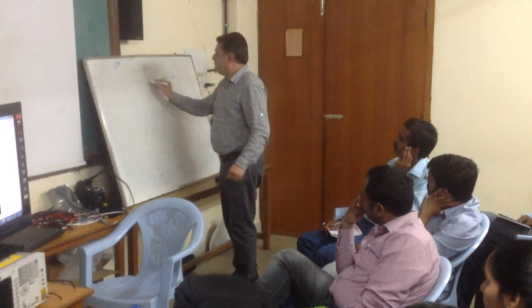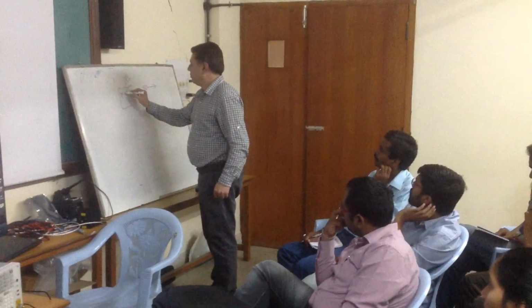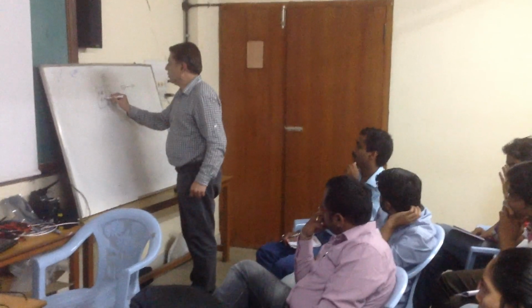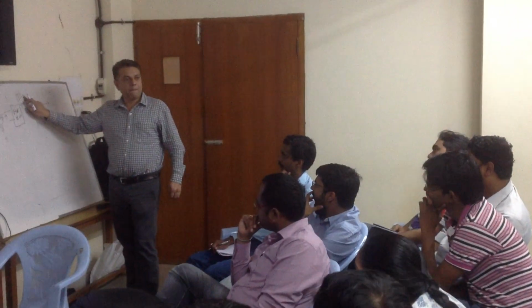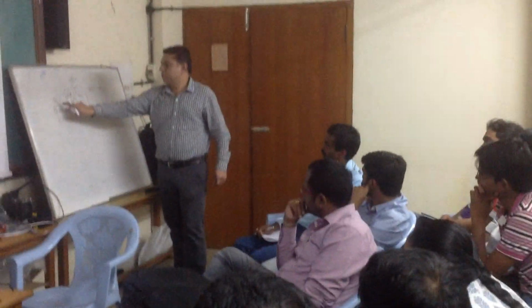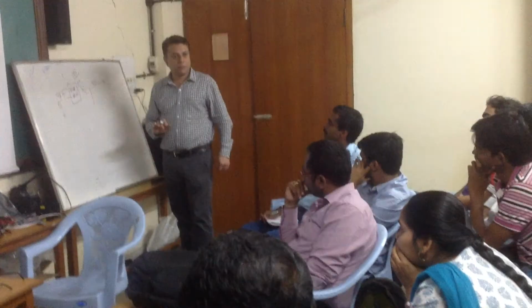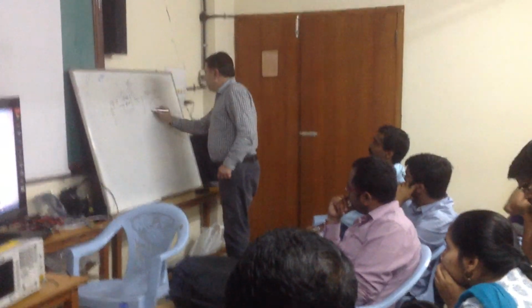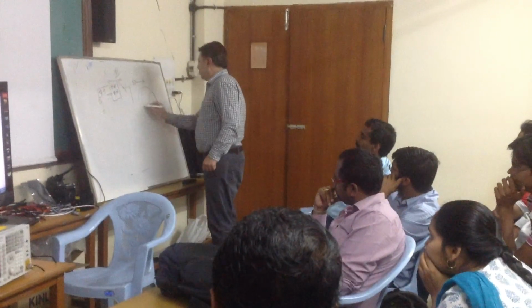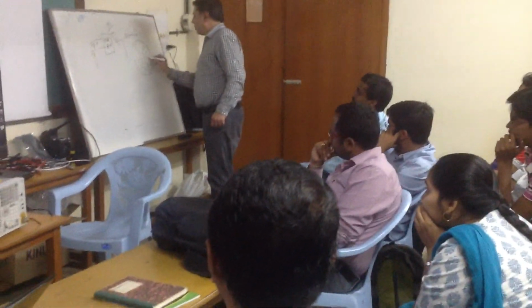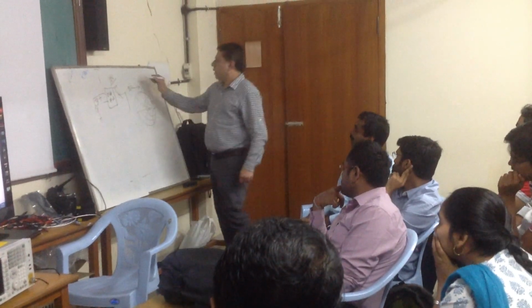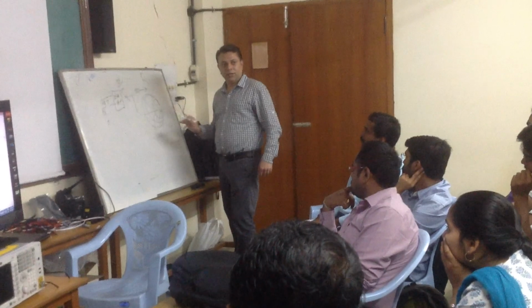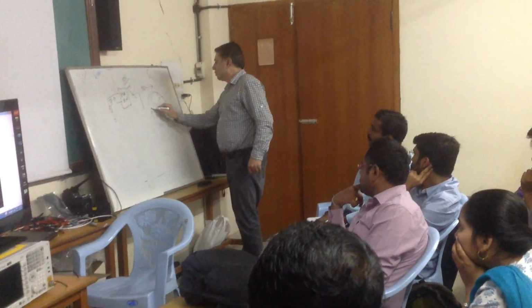So I have to design a matching network from 50 ohm, because there is a source here of 50 ohm, to 100 ohm. That was the thing. So I was supposed to design 50 ohm to 100 ohm. I'm actually doing it. Now, if you look at the Smith chart, this is how the normal Smith chart comes. You activate the Q plots also, along with these Q curves. You start getting this on top of that.